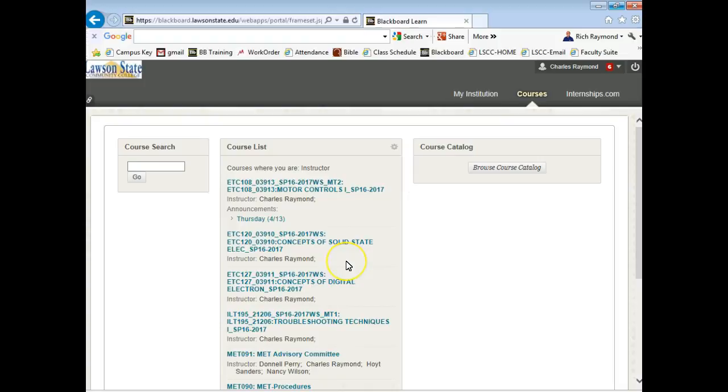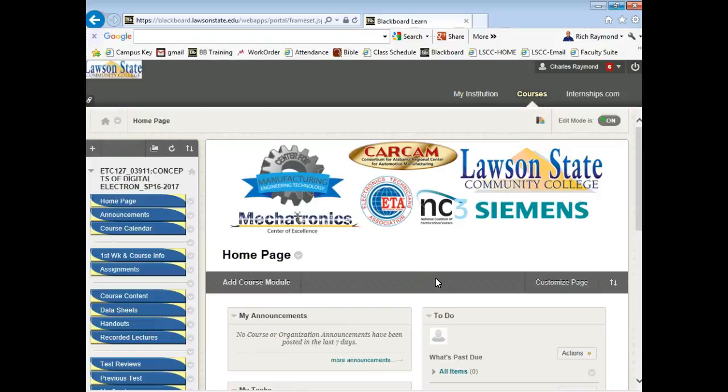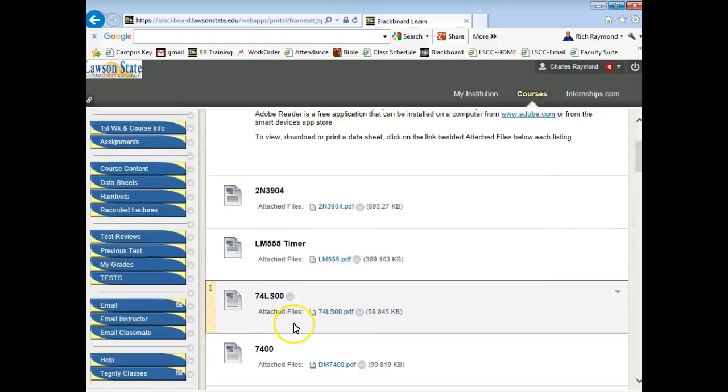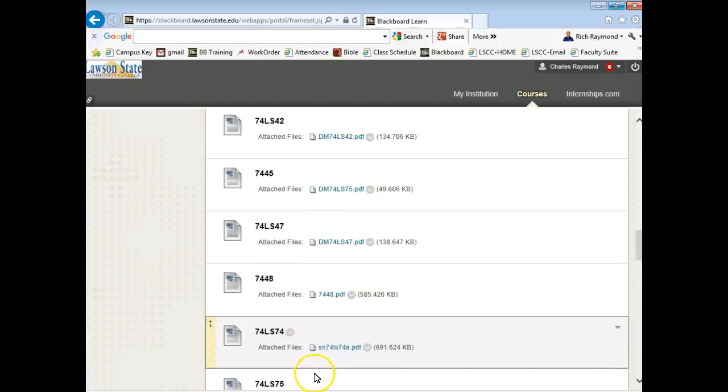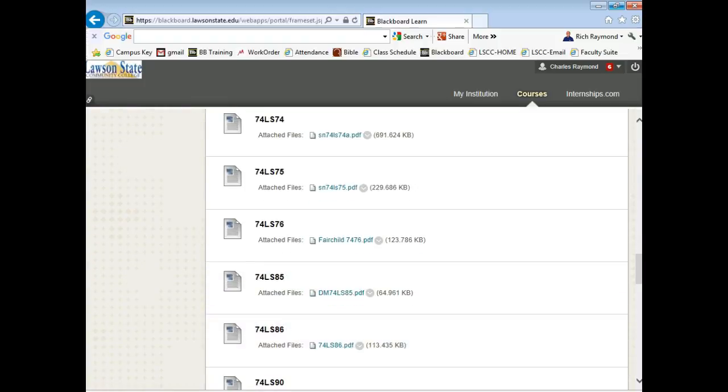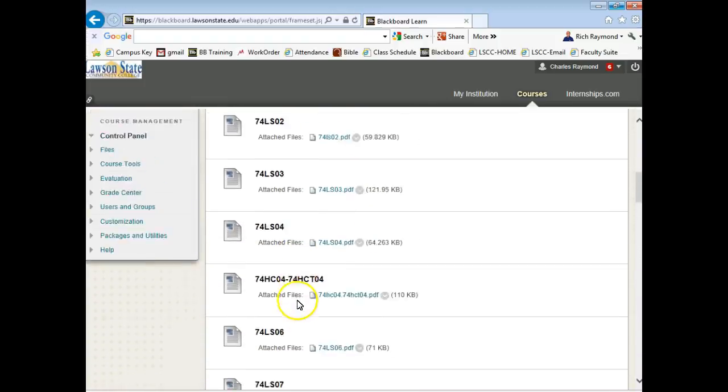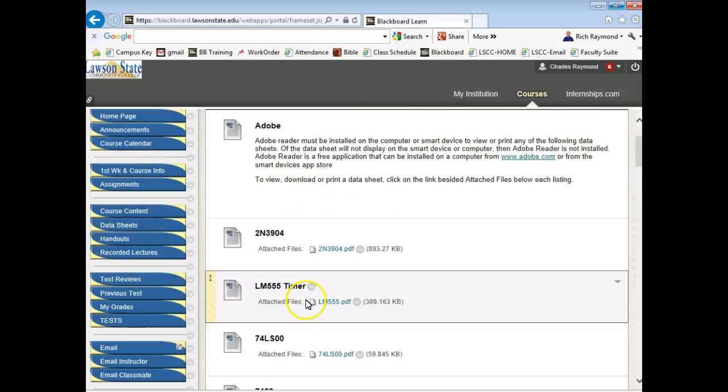Yeah. So that's the 7-segment display we're using. It's got 2 power pins. You don't have to hook both of them. What they do is just to make it more convenient when you put these things on a circuit board, where you put the power pins in. The one we got has the same pin spacing as a 14 pin dip. So what that means is that we can put this thing inside a socket, right?